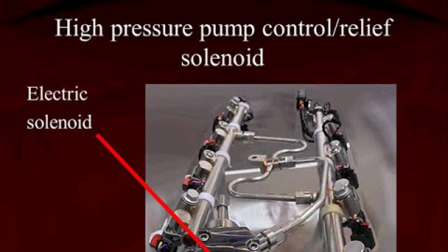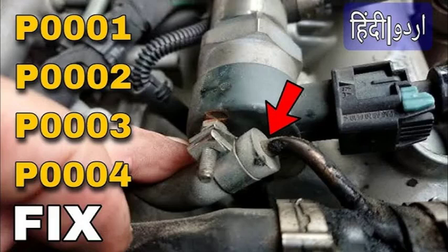The P0002 code indicates a problem with the fuel volume regulator control circuit. This circuit is responsible for controlling the amount of fuel that is delivered to the engine. When this circuit malfunctions, it can cause the engine to run poorly or even stall. There are a few things that can cause the P0002 code to be set. These include a faulty fuel volume regulator, a problem with the wiring or connectors in the fuel volume regulator control circuit, or a problem with the engine control module, ECM.